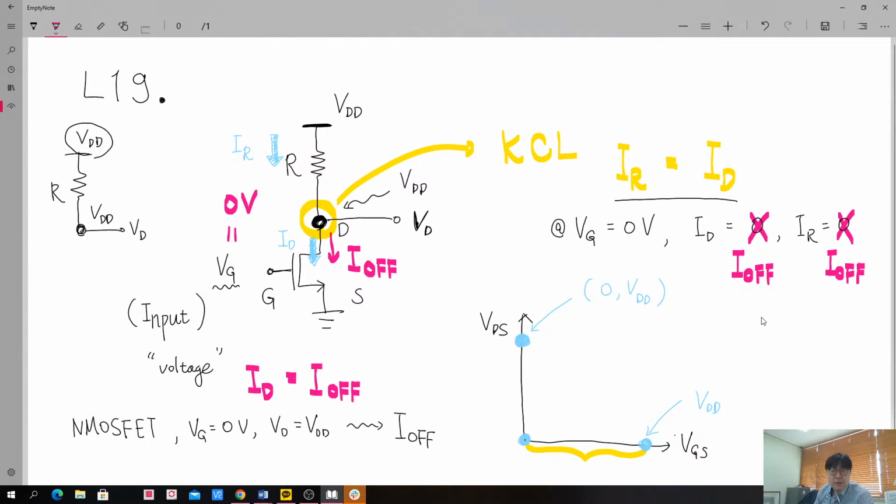We have to have a voltage, although quite small, applied to our resistor, given by R times Ioff. Once again, I want to stress that Ioff is really small in reasonably good technology, so this voltage drop would be quite small.